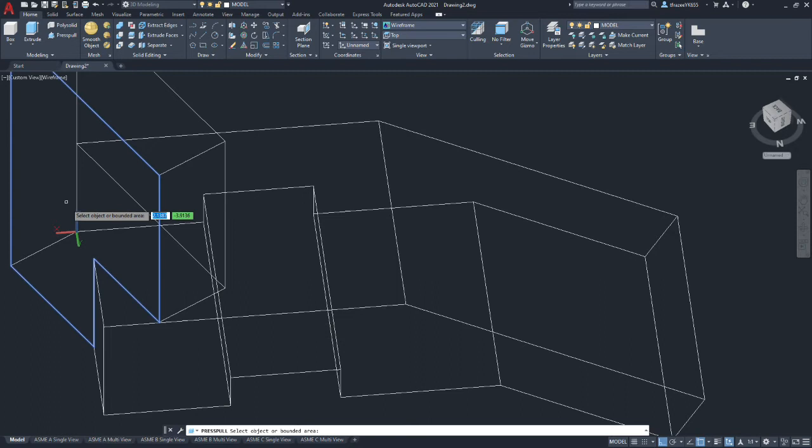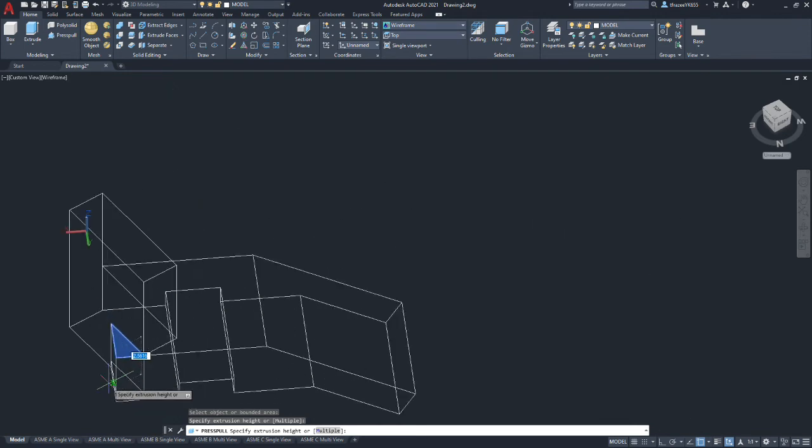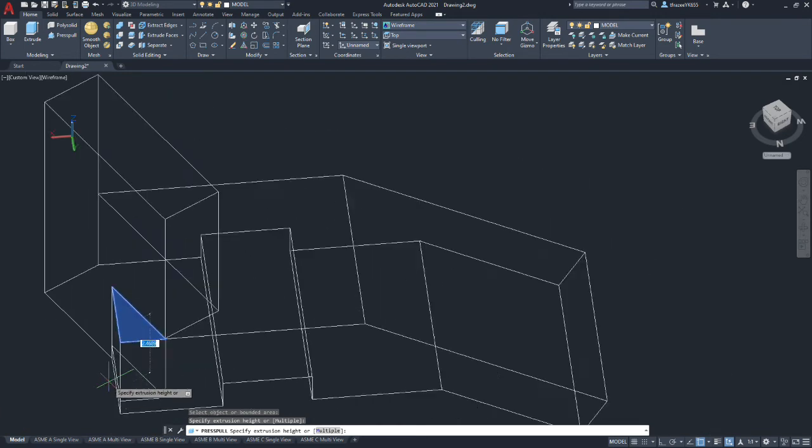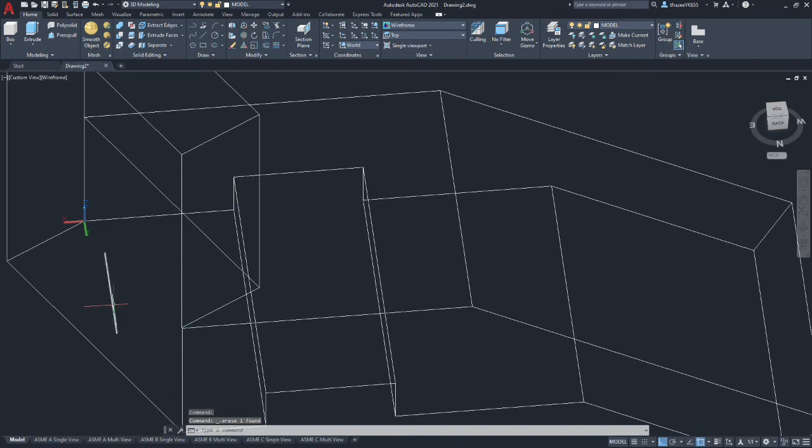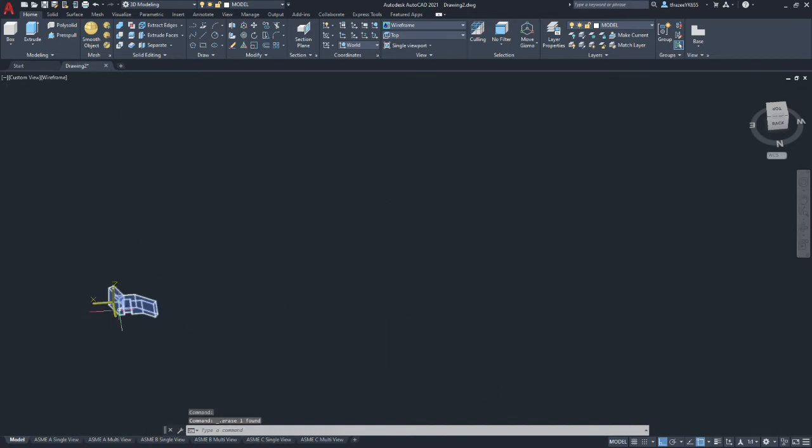We're going to go press pull. We're going to select the triangle, and we're going to go all the way through the part, and we will put in a depth of 3 inches. Alright, so we've trimmed off the tab. We're left with the geometry for the triangle. We can now delete that construction geometry because we don't need it. Alright, moving on.